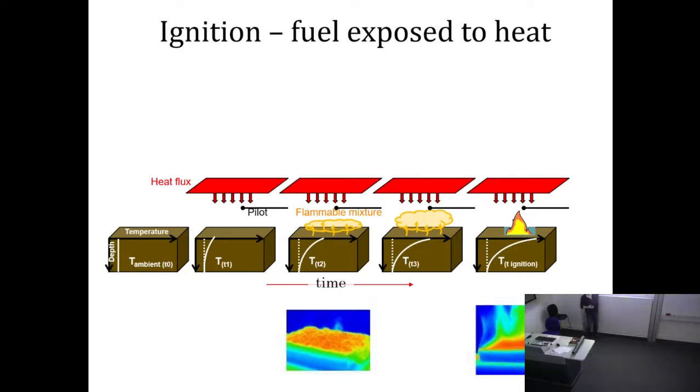It undergoes pyrolysis, it becomes gaseous. It's not really a vapor because it's irreversible. It cannot go back into the solid. So it's a gas already, it's a gasify. And it's not the same chemical composition as the solid. In the process of degradation, at the beginning there are short chains, and later on, as the process of pyrolysis continues, it might actually be longer chains. And what it leaves behind is either melt polymer or a char polymer, or nothing.